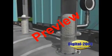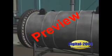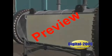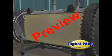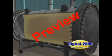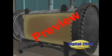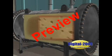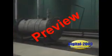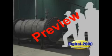With the lines and pressure gauge now sealed off, workers would have no reliable way of determining whether the tank was under pressure. As the outside of the waste tank gradually cooled, a hard plastic layer several inches thick formed around the inside surface of the tank. But closer to the center, the plastic still remained hot and molten. Unknown to workers, a slow decomposition reaction was occurring inside the molten plastic. Over a period of hours, the hot plastic molecules were breaking down, forming gas bubbles and causing a dangerous buildup of pressure.